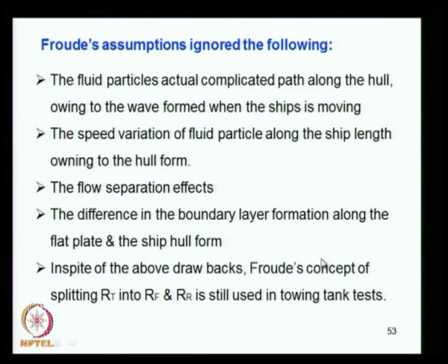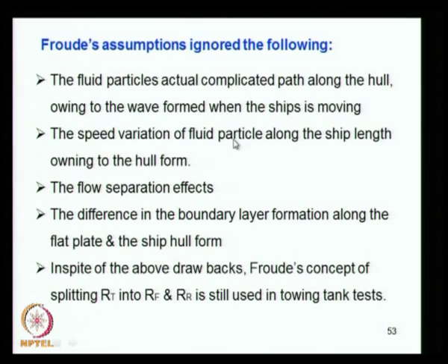The Froude assumption led us to estimate the splitting of total resistance into residuary resistance and frictional resistance. When it is done, the following things are ignored in that assumption. The fluid particles' actual complicated path along the hull owing to the wave formed when the ship is moving.